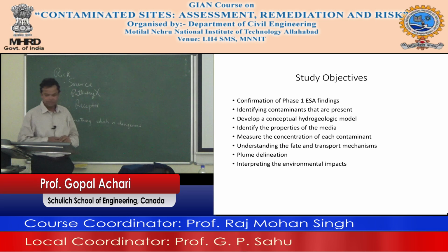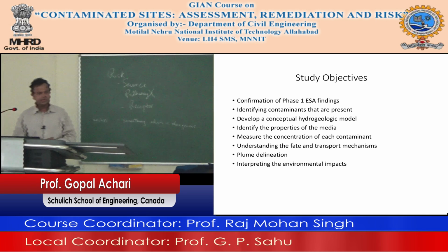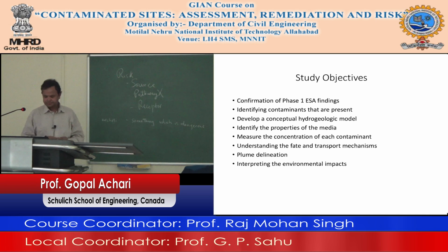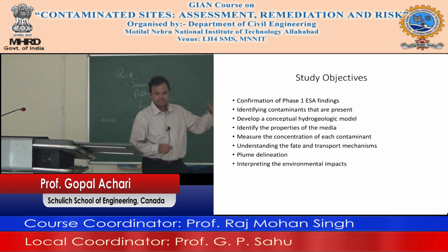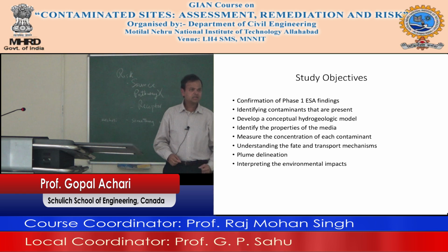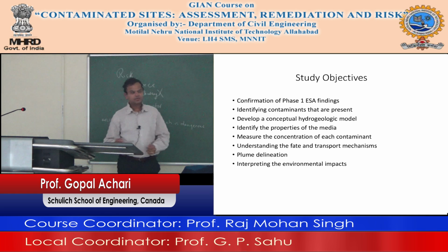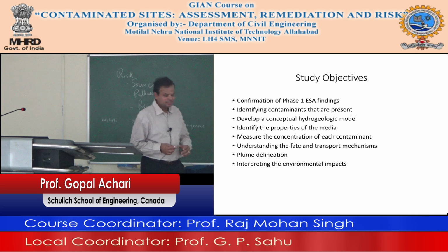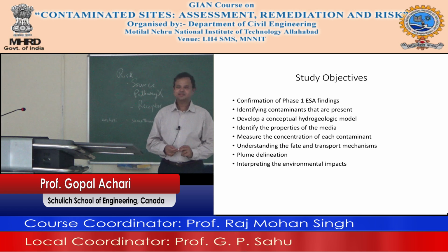So this is where you have to develop a conceptual hydrologic model, identify the properties of the media, the soil properties and so on, measure the concentration of each contaminant, drill boreholes, take samples at different depths, take soil samples, take groundwater samples, send them to a lab. And now here is the other problem. If you send a sample to a lab and say, tell me what it is, how will they tell you?